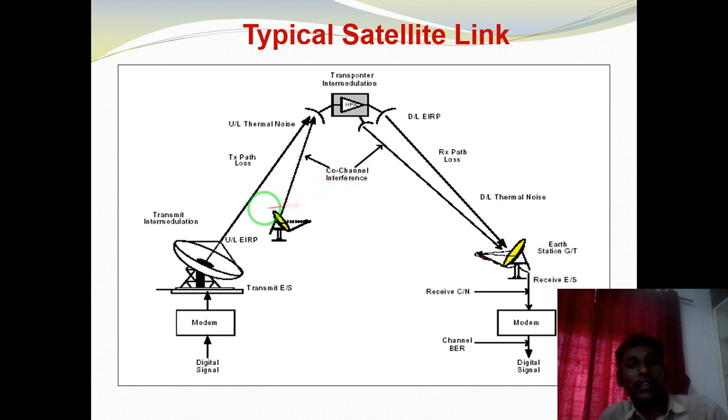Apart from the transmission path losses, the medium losses, and the interferences, there will be some losses even on the receiver side itself. The receiver is made up of electronic equipment only. When the equipment is continuously running, obviously some thermal noise will be generated. This thermal noise adds to the noise level, so that the SNR value gets low.